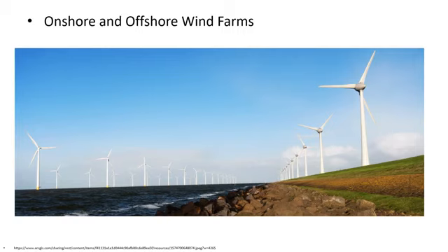Almost all large wind turbines have the same design, a horizontal axis wind turbine having an upwind rotor with three blades attached to a nacelle on the top of a tall tubular tower. In a wind farm, individual wind turbines are interconnected with a medium voltage, often 34.5 kV, power collection system and communication network.